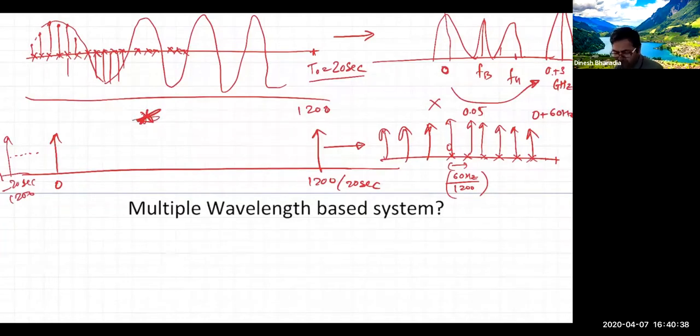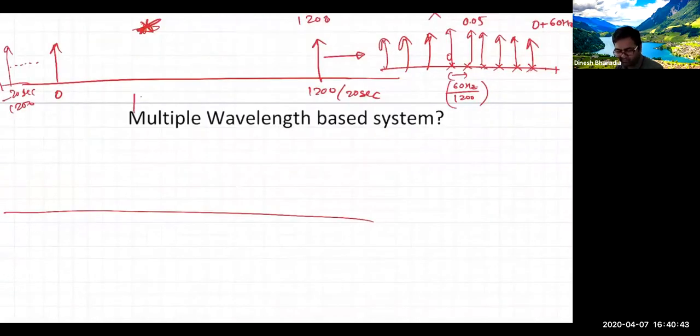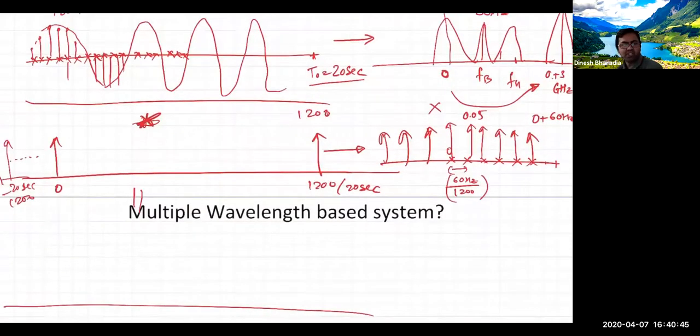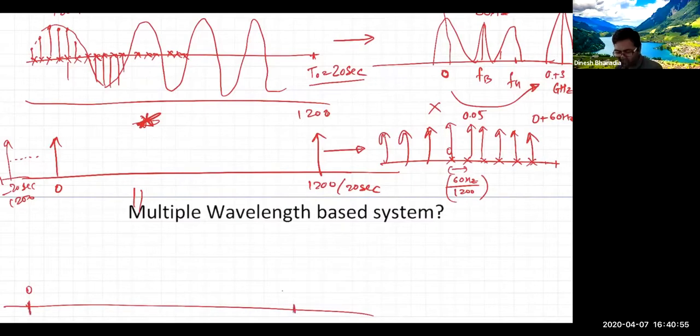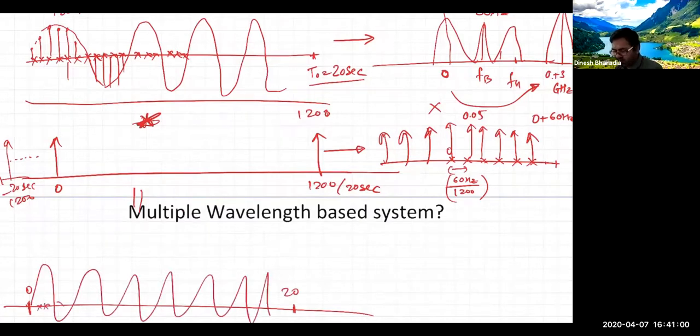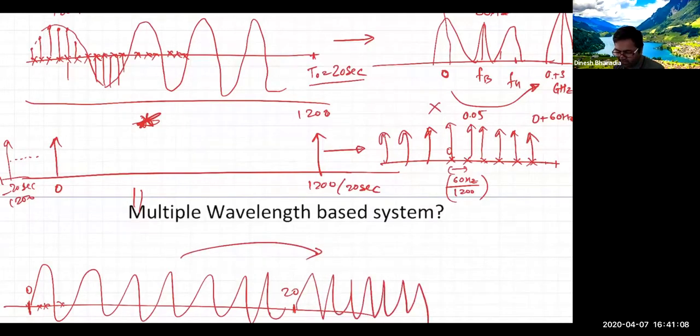What would it look like in time domain? What would happen? The output of this will be... anyone want to take a shot? You would get the periodic extension of this signal that you originally sampled over those 20 seconds. Yes. We get the 0 to 20 second signal, the actual signal sampled again, and its same copy will be repeated after 20 seconds. This is your time domain, okay?